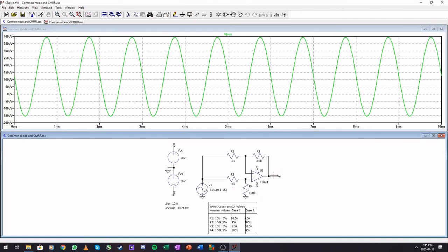and we see that this is 400 microvolts with a bit of offset. Remember, this is not an ideal op amp I'm using, so I'm also going to see offsets. And we have this signal coming out, but it is very small. Okay, so from 1 volt to 400 microvolts, it's kind of a good noise reduction. So always try to match your resistors perfectly when building this so that common mode signals are well rejected.